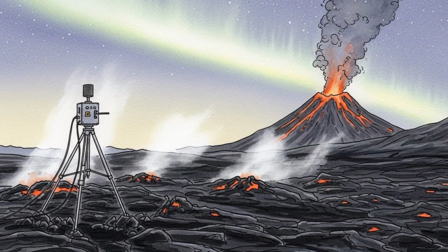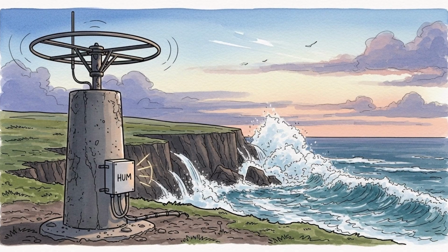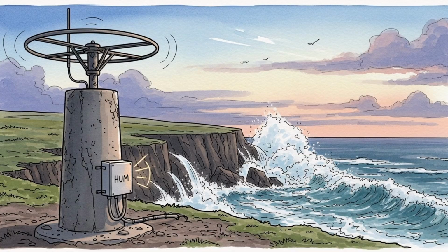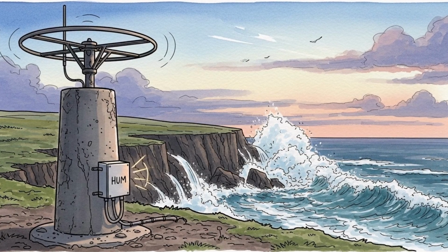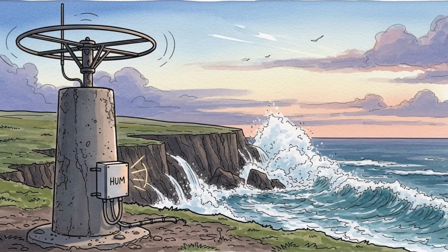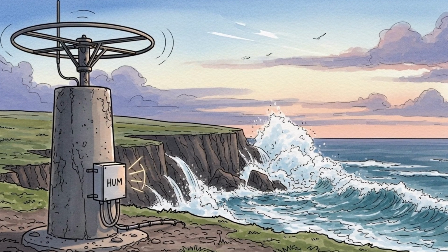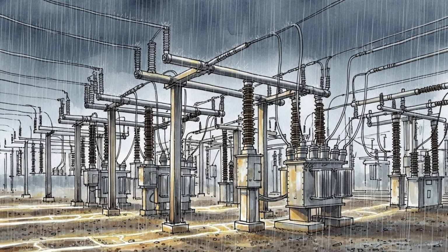Satellite communication links at L-band and S-band can be degraded by ionospheric scintillation and rapid changes in total electron content. Receivers may lose lock or require repeats at the physical layer. At higher bands such as C, Q, and K, the ionosphere is less important, and weather on Earth, like rain, remains the main impairment.